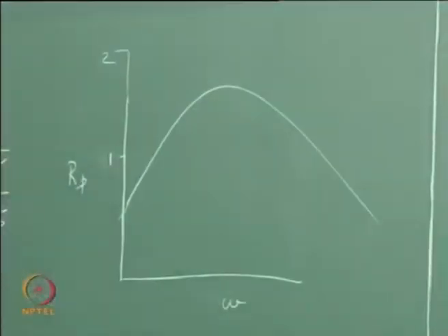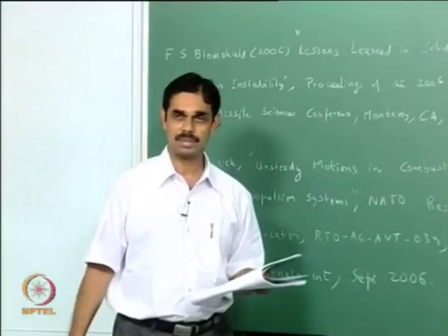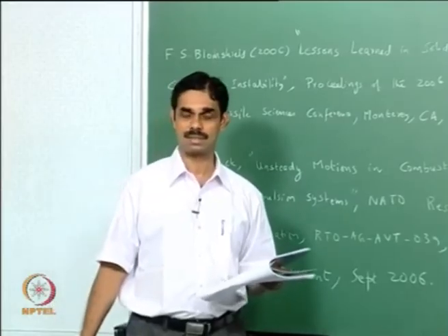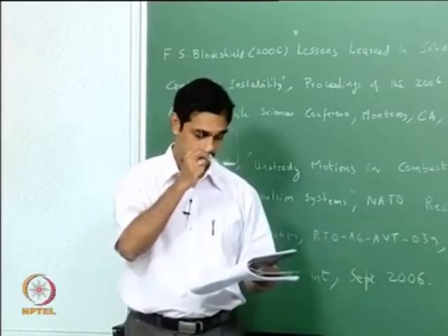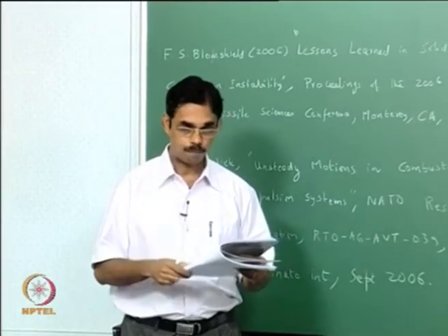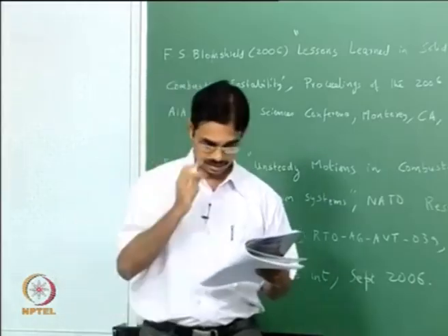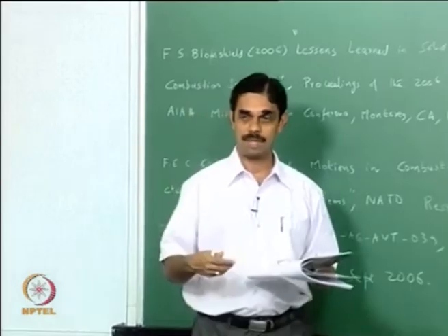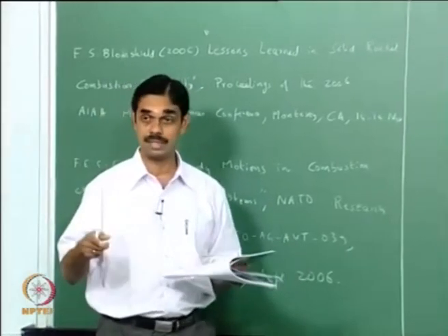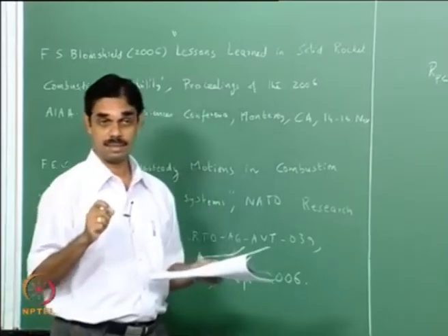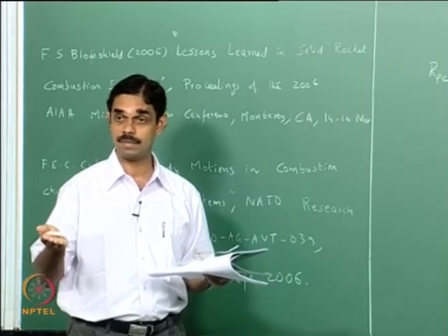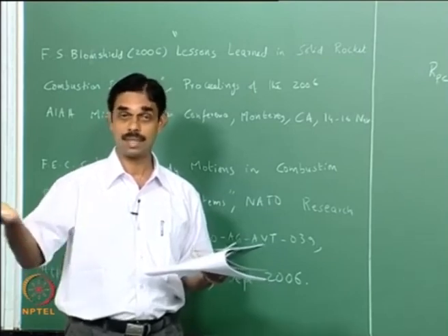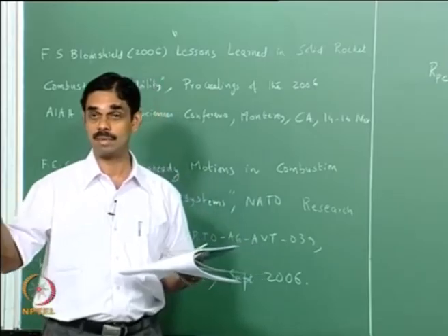You have to determine this for various parameters with experiments, and there are people trying to calculate it, but it is not that simple and not a proven calculation. I think we are still not there to calculate this properly, so we have to do experiments. And like I said, this is the most important parameter. Once again, if you think in terms of r equal to a p power n, the n gives the response only for omega equal to 0, but after that it depends very much on how the flame responds to the acoustic oscillations, and that need not be in a quasi-steady manner at all.